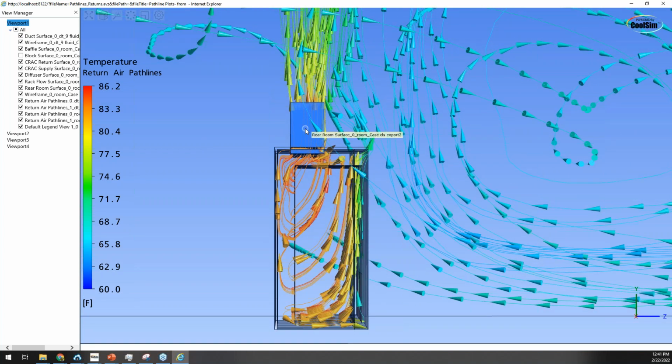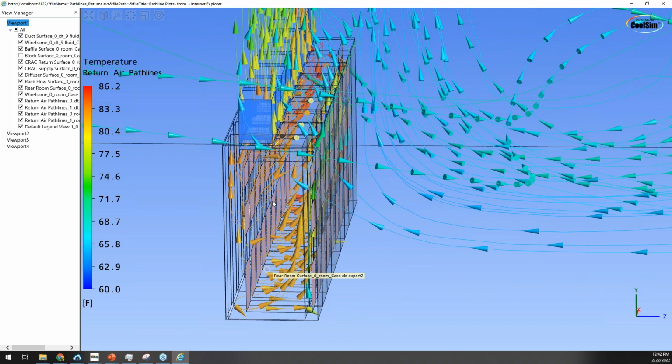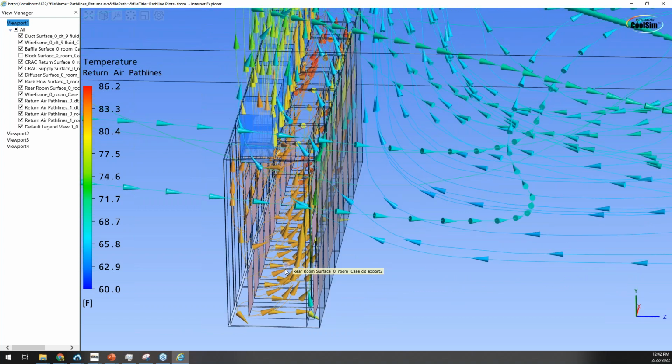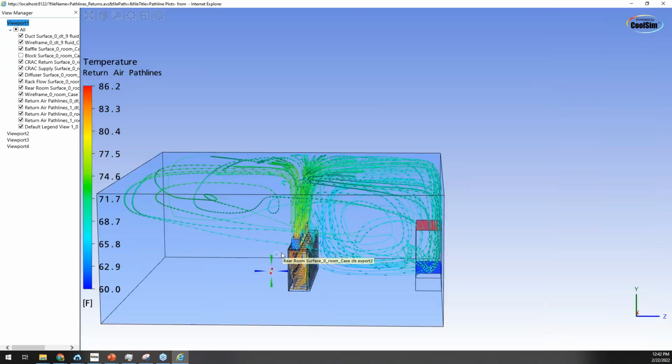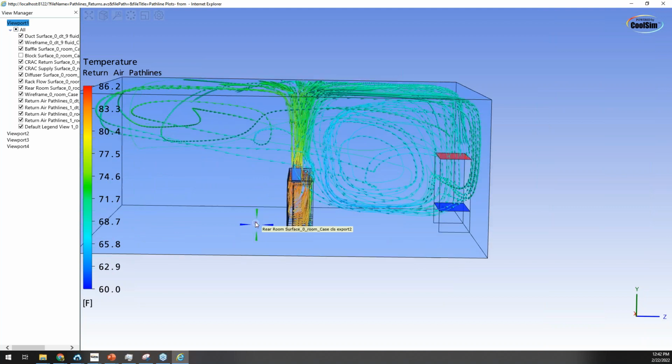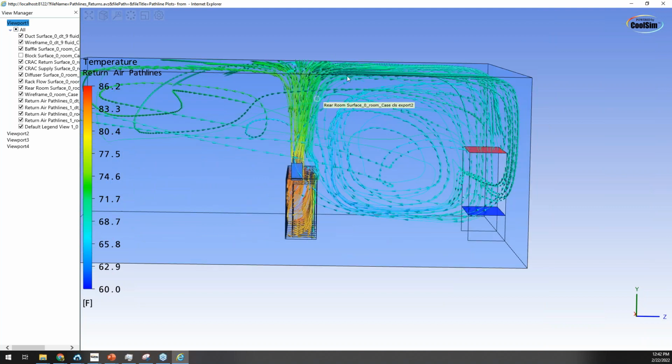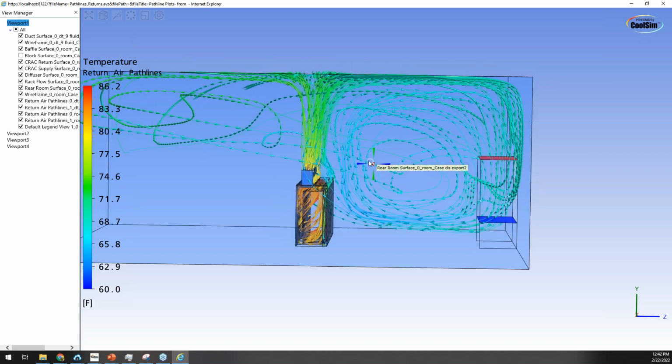Same idea with hot oil containment, same exact issue. It comes out, it bangs into something, often the other server. If they're wide enough, you're good, but sometimes they're too narrow, and it wants to leak around and come out the front. And you say, well, you've set it up incorrectly because there's no ceiling plenum there. But my point is ceiling plenums are notoriously leaky. Most ceilings in a data center are made of a standard drop ceiling kind of structure, much like we have in the basement of our homes.